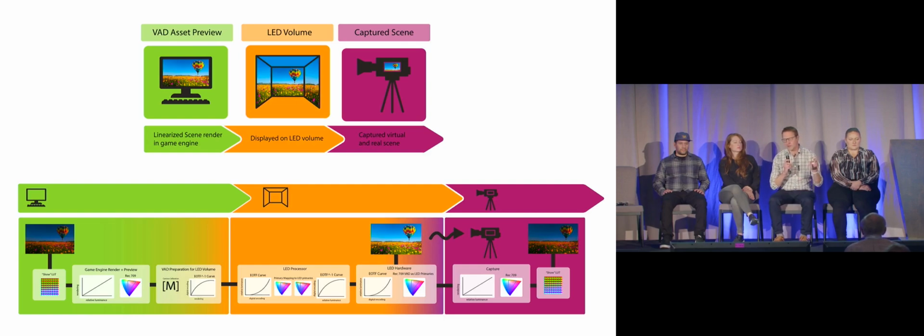Those of you who've noted I've skipped this thing called M, don't worry, I'm coming back to it in just a second, but we've got to go through like everything's perfect and then realize when it's not, we have to do calibration matrices as example. Once you've transformed the primary drive into the native for the display, that has to be re-encoded. That has to be run again through the inverse EOTF because you do not want to send linear values down a bit-limited transport layer.